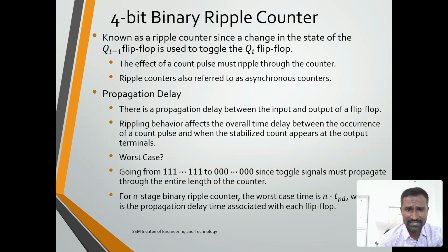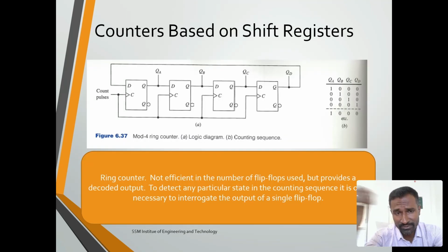And this is the explanation of how we can use counters based on shift registers. So this is the diagram I'm trying to show. See the counting of QA, QB, QC, QD. I'm taking the outputs in parallel at the same time. Giving the input as D, only the first bit is enabled, and that one will be passed to the next one upon giving the second clock pulse. For the third clock pulse, the one is forwarded to the next one. At the fourth clock pulse, it reaches the fourth one. Likewise, at the fifth clock pulse it automatically comes back to the first position.